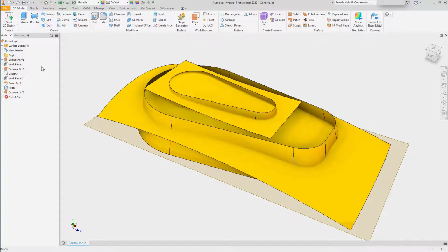First, we have Extrusion 2, which rises above Extrusion 3. I want to use Extrusion 3 to trim Extrusion 2 to give it a more complex top edge. So in the surface panel, which was turned on using the pull down on the 3D Model tab, I'll select the Trim tool.